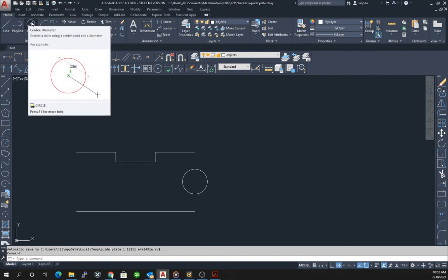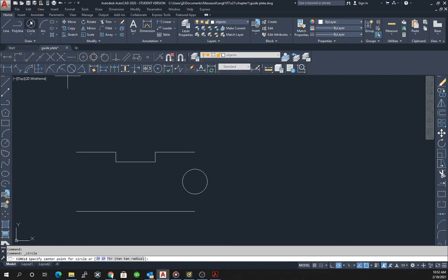I'm going to do the same thing I did previously. So I choose circle, I get my snapping line, I move up, get my tracking line, type 1.5. Again, remember, excuse me, let me place this first. When I get that little square here, I don't hit my mouse button. I just slide away from it to get the tracking line.